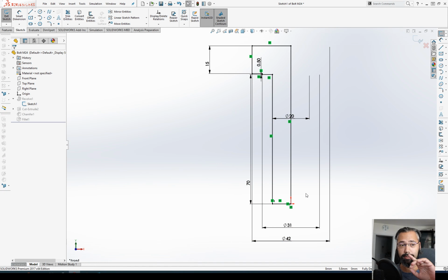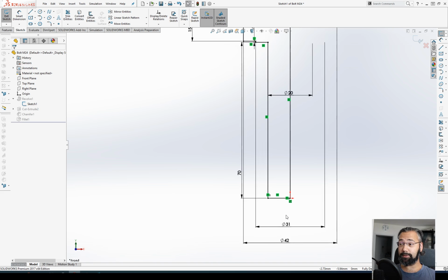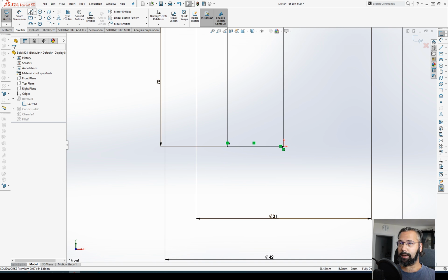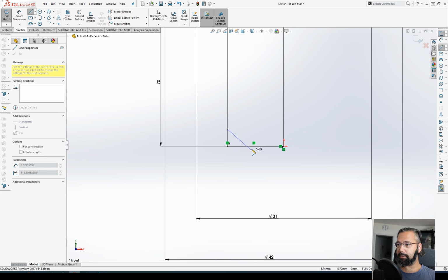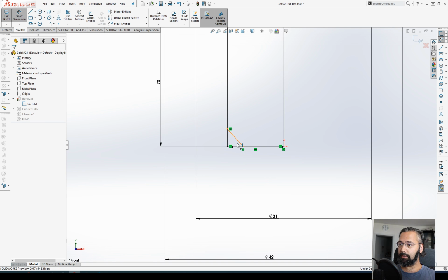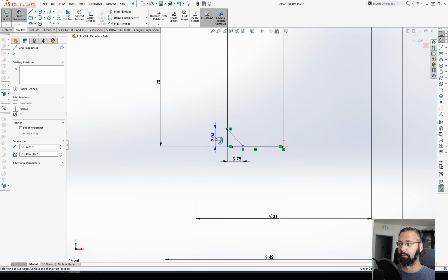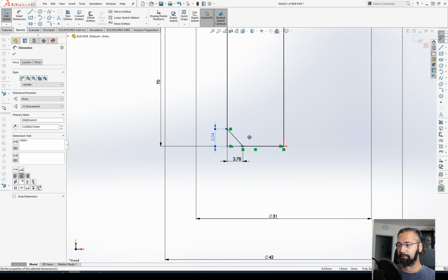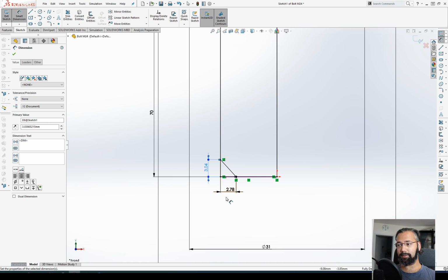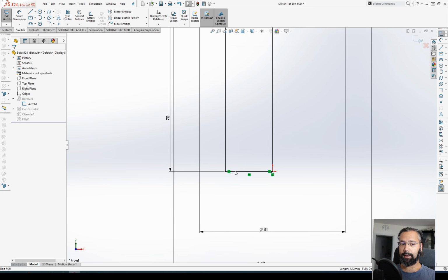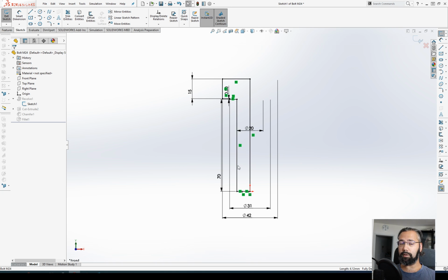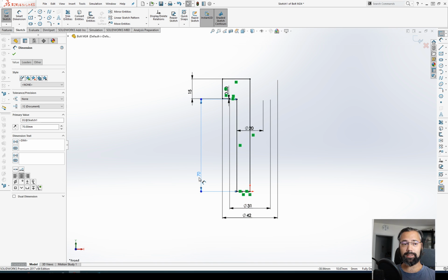Another thing you should avoid at all costs. A lot of people will, instead of what I did, you might be tempted to go and do this to give the chamfer that I put later as a feature. You don't want to do that because of one reason: how robust your design is.